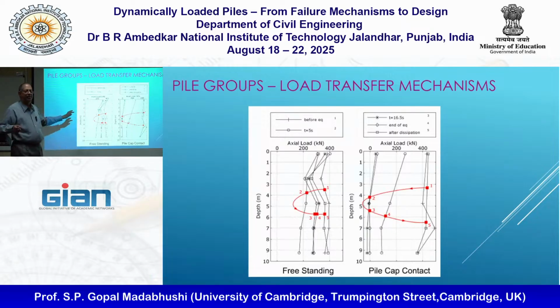There are many examples where, if you have liquefiable soil, you drive piles into dense sand below. Even Delhi's Akshardham temple had piles like this. So many examples I can give. When the earthquake happens, the bit they ignored in their design is what is going to save them, which is a bit scary.